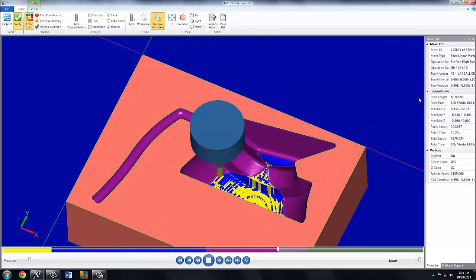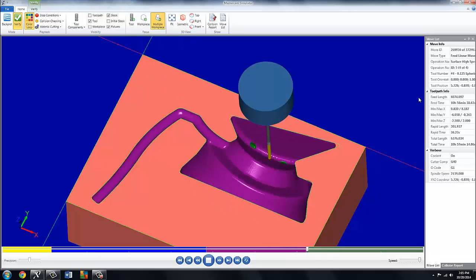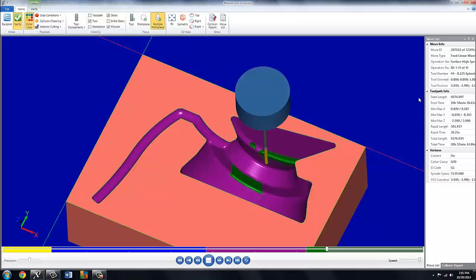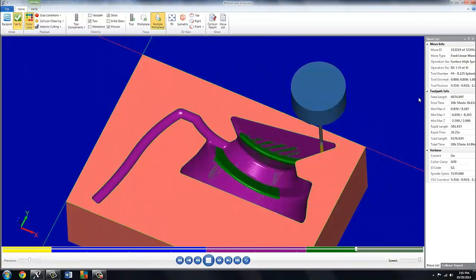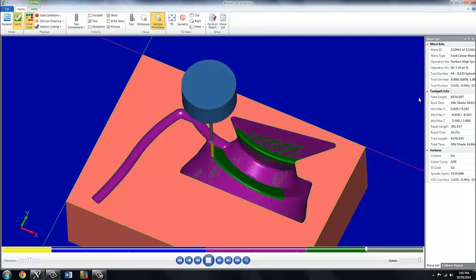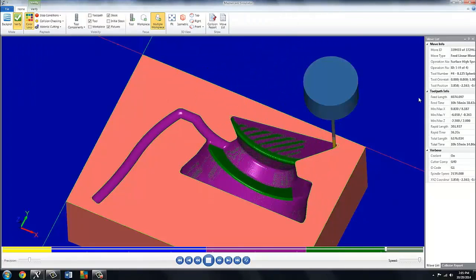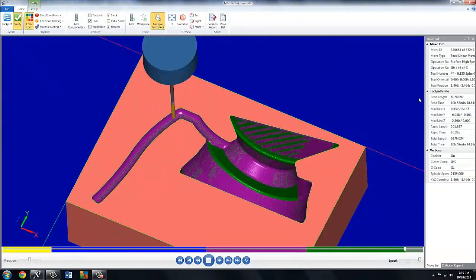Had to get out that special long tool because my holder crashed into the side without it, which makes sense. We're pretty deep here picking this out. Didn't do it with the bigger end mill because they're usually a little bit longer. But a long skinny end mill is usually something special, so we took care of it. You can buy any tool you want, you can have it made. There's plenty of vendors out there who will make things for you.